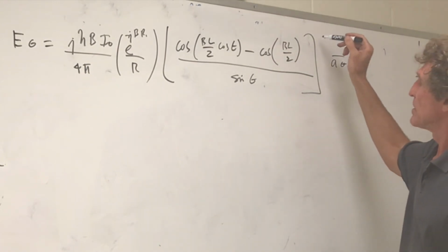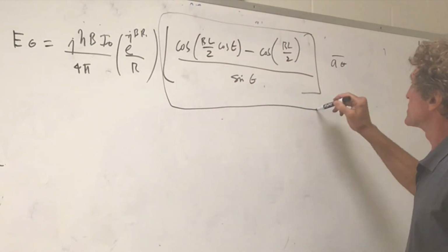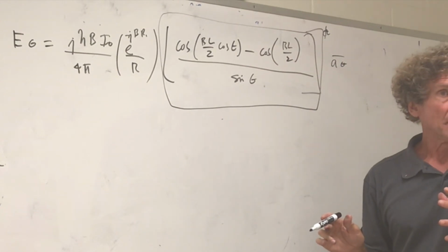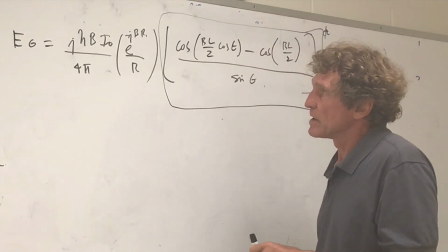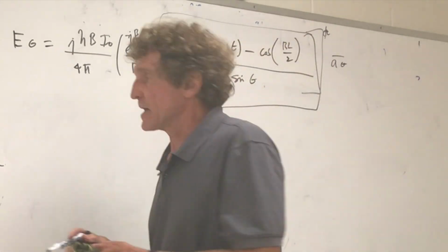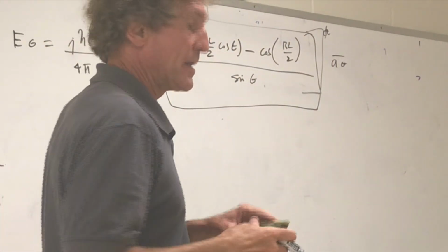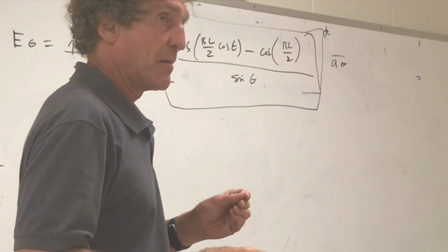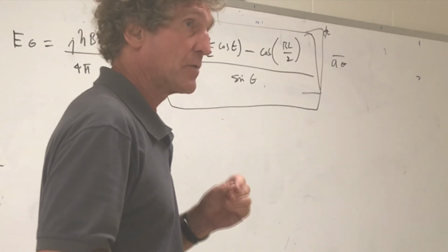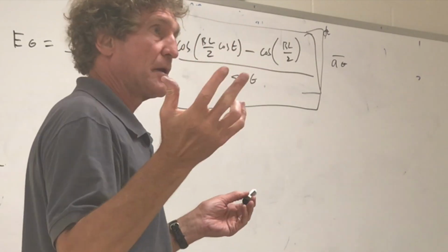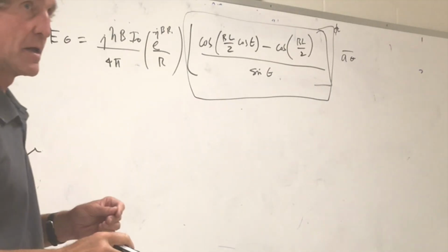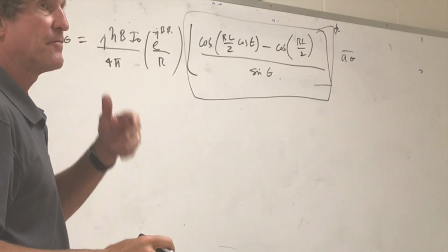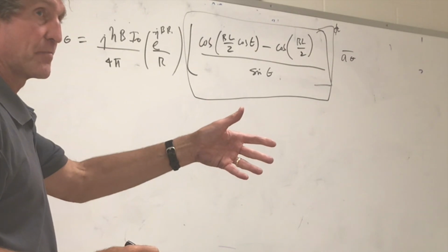This right here is an angular function. It's only a function of angle, right? So typically what they do with a dipole antenna or anything like that, they're going to call that, well, this is called the electric field pattern or magnetic field pattern, but the power pattern would be that squared. Are you with me, class? In terms of angular function, I'm going to ask you something. That's the electric field. The power would be proportional to the E field squared. Do you agree with that, class?